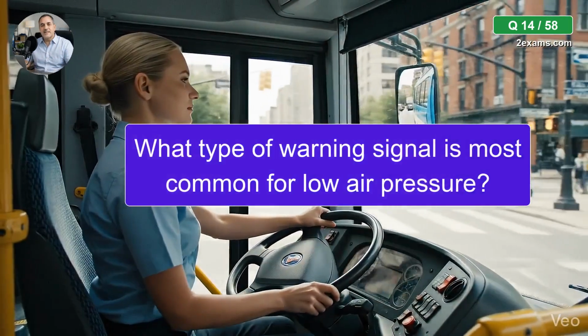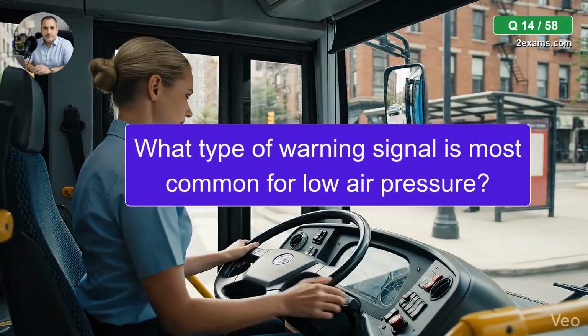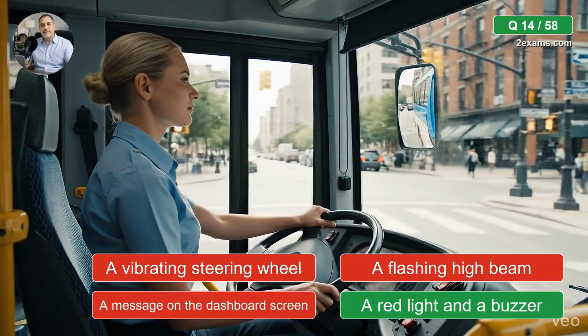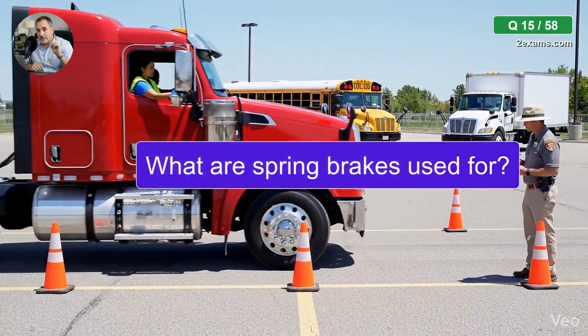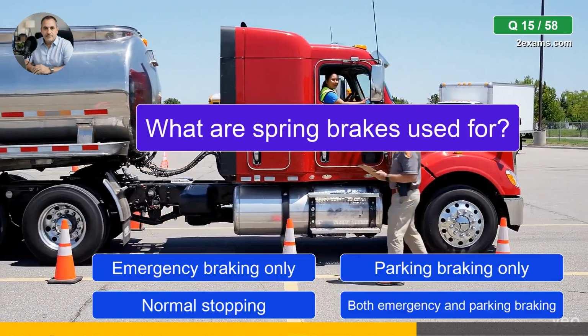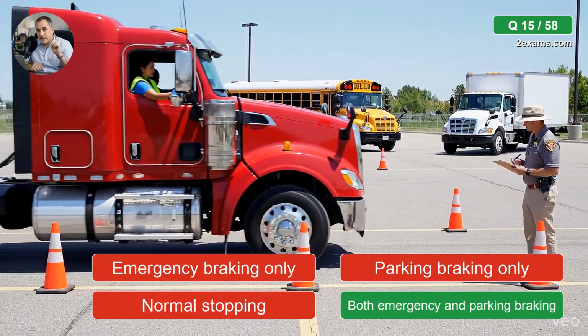What type of warning signal is most common for low air pressure? The correct answer is a red light and a buzzer. What are spring brakes used for? The correct answer is both emergency and parking braking.